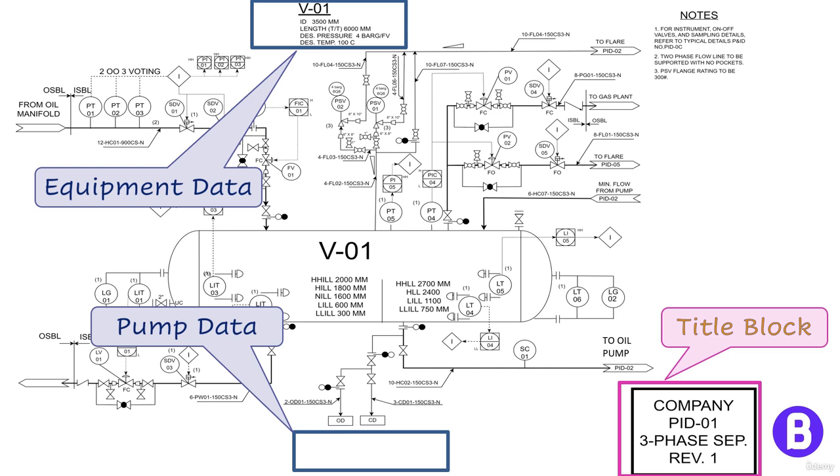This is because most probably we shall have a set of P&IDs to cover this scope. Commonly, a project may contain more than 10 P&ID drawings, and we even may find ourselves needing hundreds of drawings in large projects. So, to control these drawings, we need to assign a P&ID number to each drawing. So we should assign a unique number related to each drawing to distinguish it from other drawings. This is a very simple numbering system, but the numbering system can be much more complex depending on the system to be followed.